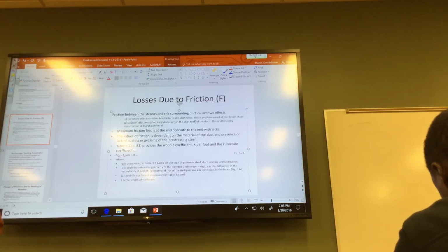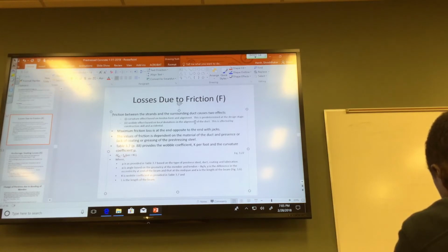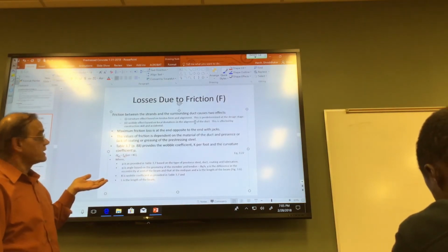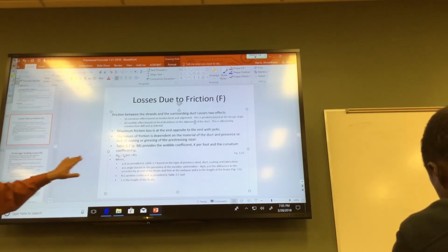If your duct is very soft, for example, and you pour the concrete, it's going to pinch into an ellipse that you thought was a circle, right? Or worse yet, somebody has really pinched it, now you're going to rub against it. So it depends on the skill of the construction, for example, right? So it depends on how well it's done and what kind of material, soft or hard, you're using, right? So it depends on that.